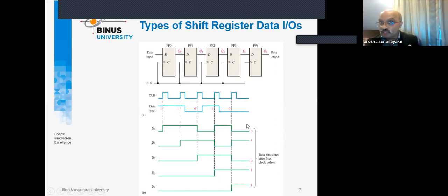But of course, in serial data, just to show only this. So then in the pulse, you can see that Q0 holds on for some time before being changed. That is the key point in this case, and that's very important. So during the clock pulse, the data in Q0, for example, is available steadily, without changing.